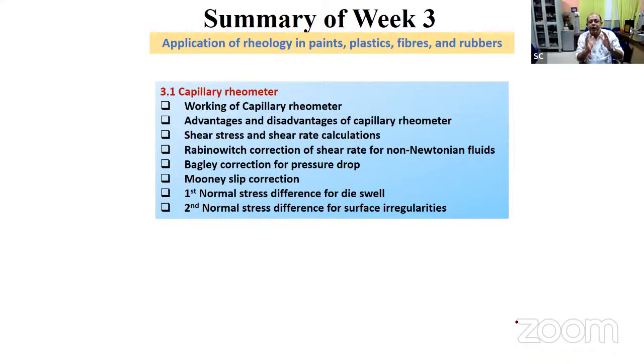Then we went into the application of rheology. So far we understood rheology, okay? Then how to apply it, okay, in paints, plastics, fibers, and rubbers. We talked about working principles of the capillary rheometer. We talked about advantages and disadvantages of the capillary rheometer, shear stress, shear rate calculations, Rabinowitsch corrections,